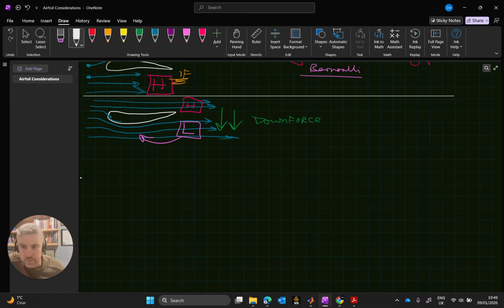It's a non-dimensional number, which is generally given by the density of the fluid multiplied by the velocity of the free stream, as opposed to near the wall, and on flat plate theory, the characteristic length, L, over the dynamic viscosity of the fluid that you're running in. A dimensionless number.